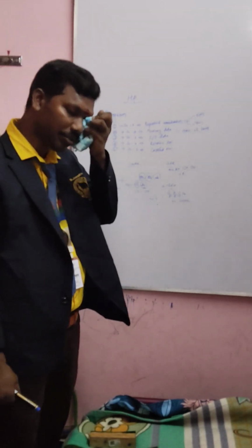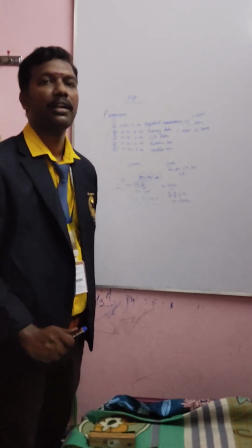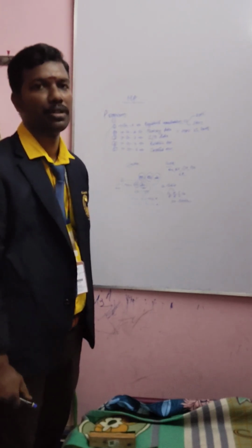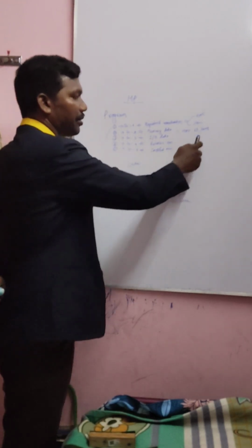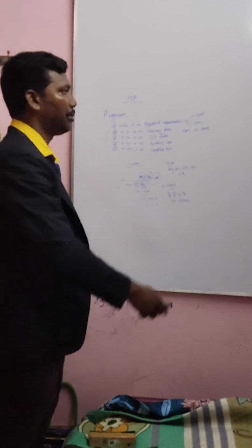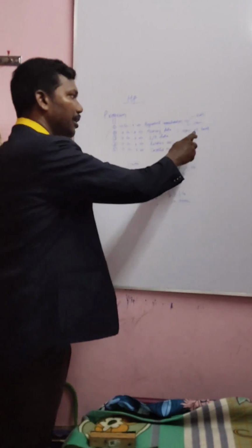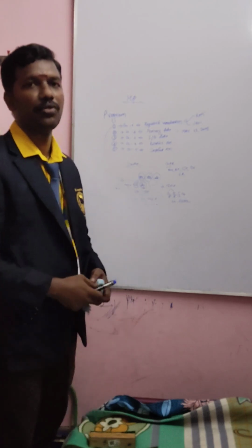What is the meaning of 4200 along with the bracket? That bracket represents pointing to the address. This is a very important, crucial thing. The square bracket will represent the address. Suppose instead of the square bracket it is without one, then we call it data. So the memory location, the address, holds the data, and that data will move to the SI, the source index register.